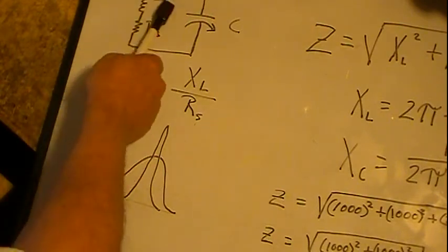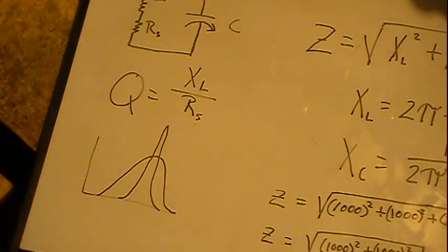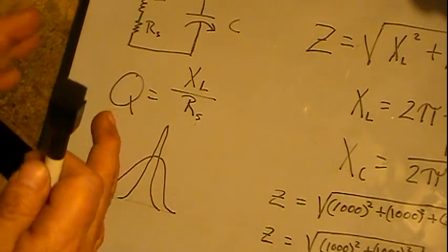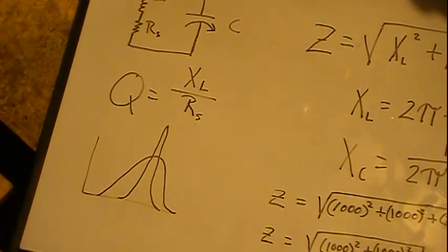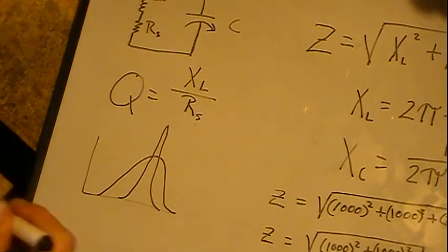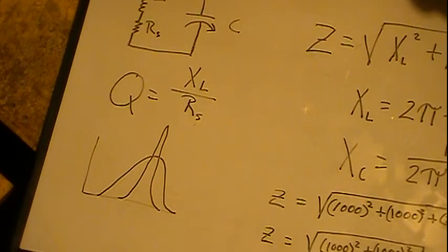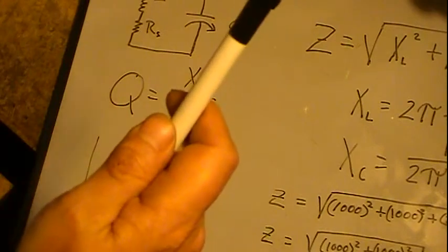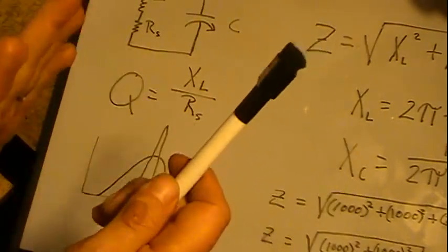Now, on an antenna circuit, you're going to want somewhat of a wider bandwidth than what you might normally think. And the main reason is something I haven't talked about yet, and I'll have to do in one of the theory videos, and talk more deeply into it, is sidebands. You have your carrier frequency, and then you have two sidebands, the upper and the lower sideband.